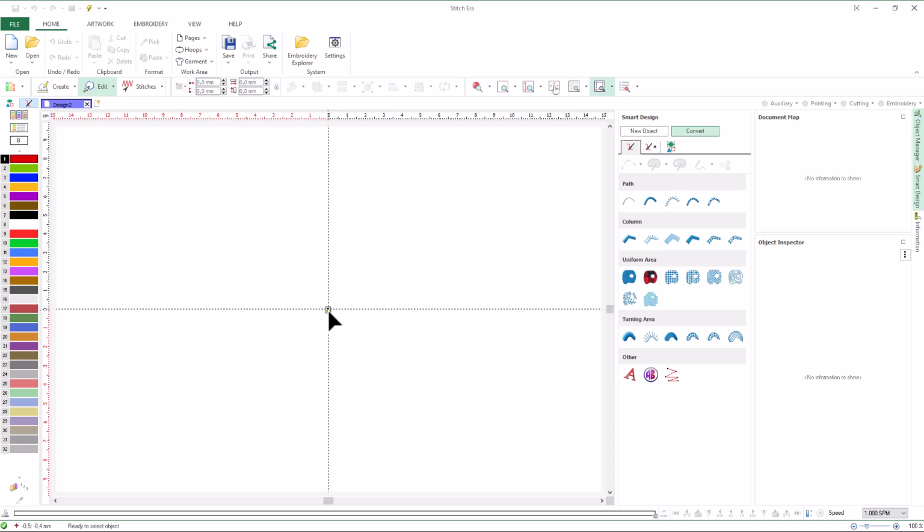In vector images, the contours of shapes are already defined in the objects that make up the image. When we create our embroidery objects from a vector image, we use those same contours, without the need to digitize them. In pixel-based images or raster images, there are no contours, but only regions of different colors. To create our embroidery objects, we need to digitize those regions.